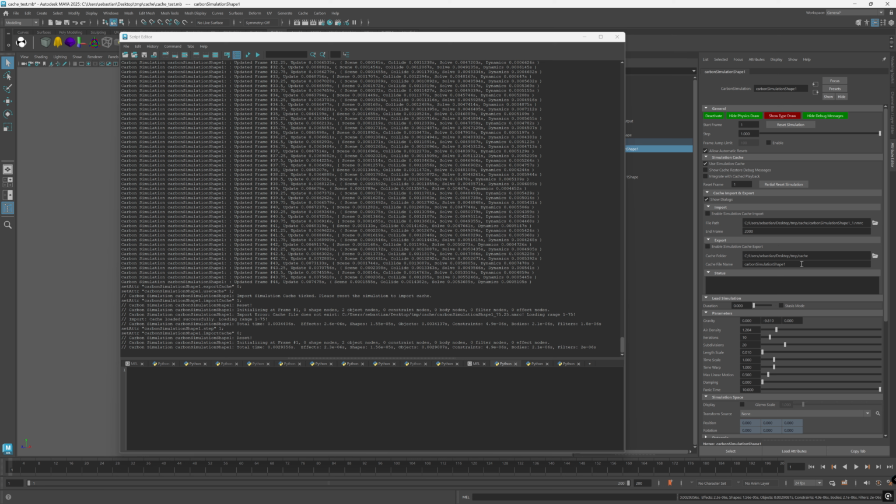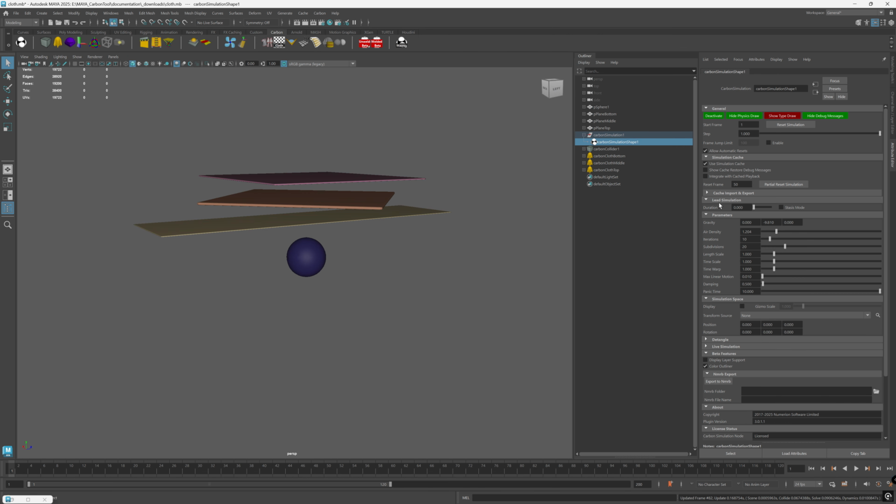It can also be very useful if you want to simulate a long scene, and you might want to make some changes halfway through because you get some behavior you don't like, but you like the first 100 frames. So why not save out the first 100 frames and then keep import on and set to 100 frames. So it will always load the first 100 frames into cache, and after that you can make changes to the parameters and simulate on. We have a lead simulation example, which I will just bring up quickly.